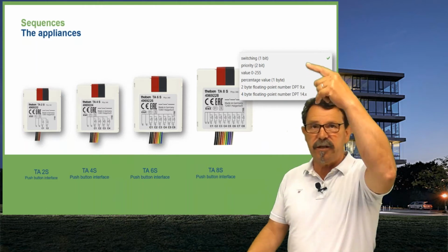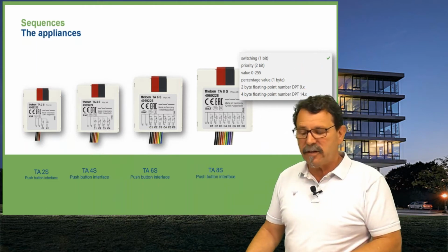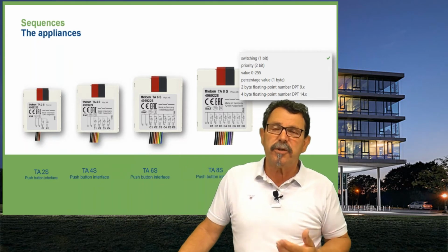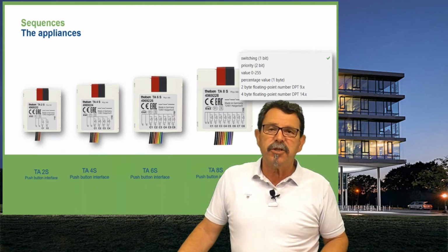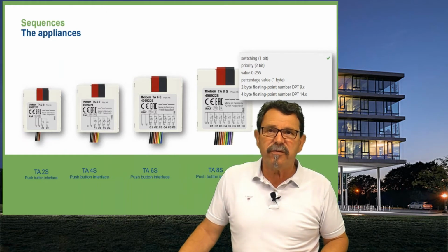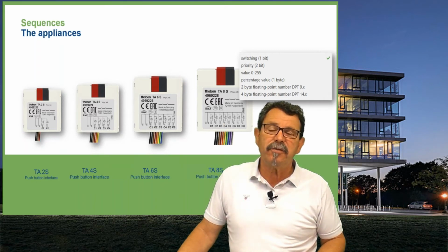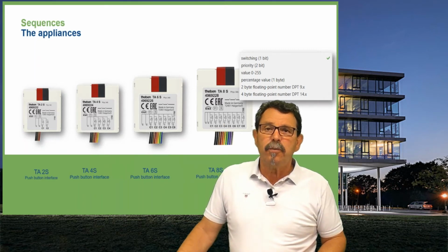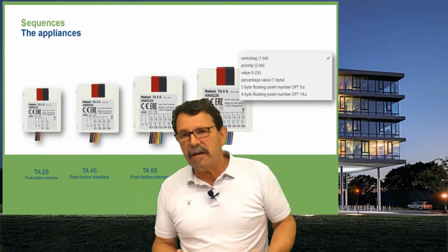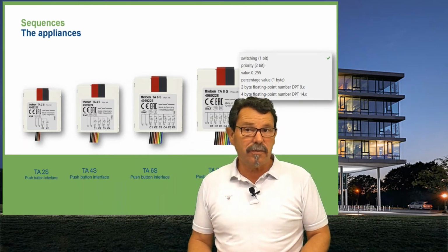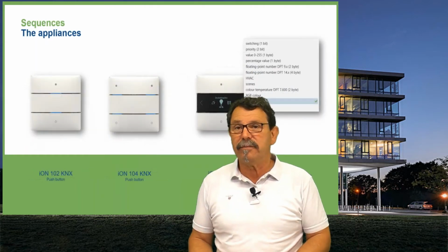We have some control commands which we can send: a switching, a priority, a value 0 to 255 percentage value in 1 byte format, or data point 9, data point 14, for instance, which we can use finally for a sequence control. Is this all? No, by far not.